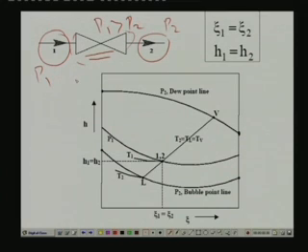If you apply mass and energy balance, you will simply find that the composition remains constant and the enthalpy also remains constant. So, if you try to show this throttling process on the enthalpy composition diagram, you will find that both inlet and exit are at the same point. That means they are identical. Why are they identical? Because enthalpy is the same, as this equation shows, and concentration is also the same.